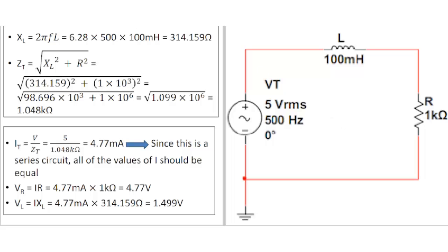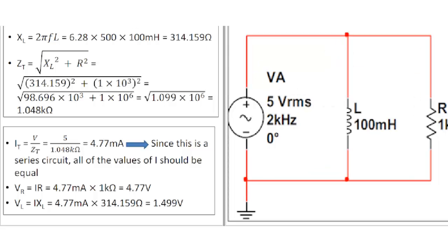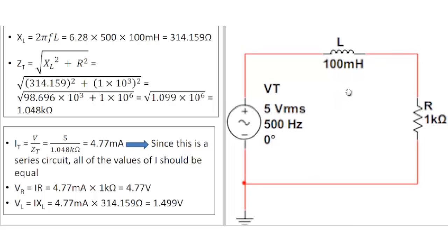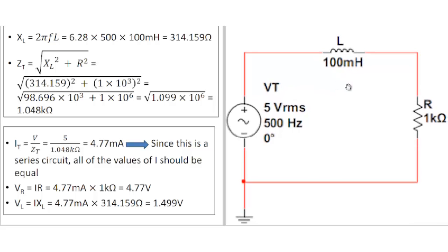series LR circuit. A couple of questions should come to one's mind when you look at circuits like this, whether it's inductors or capacitors or anything. Ask yourself, what do the components in the circuit have in common? In this particular case, what these components have in common is current flow. So current flow is not going to be used to analyze deeper the aspects of this circuit. You would use what's different about these components, and that's the voltage drop.